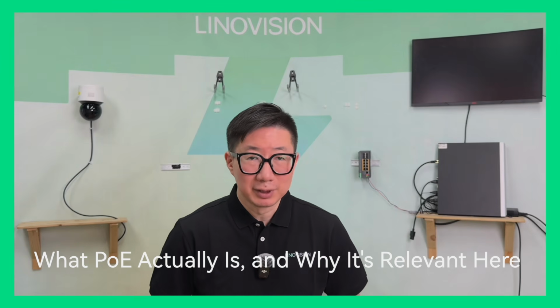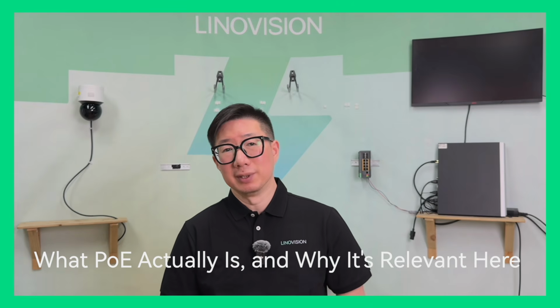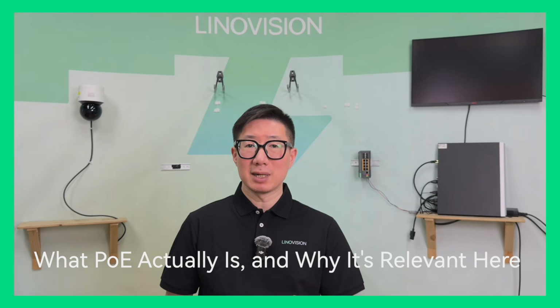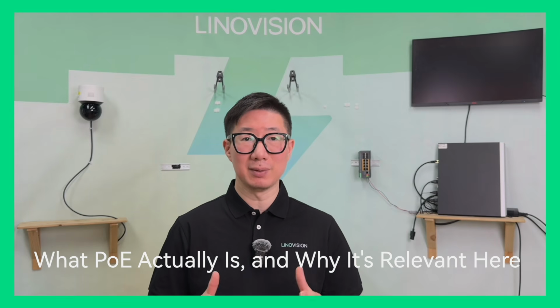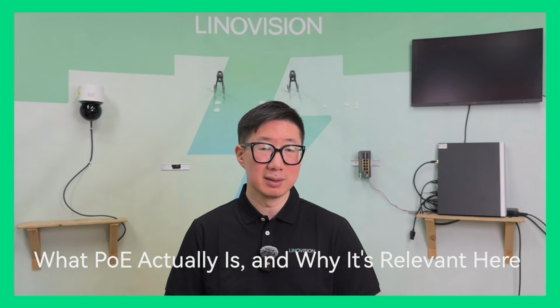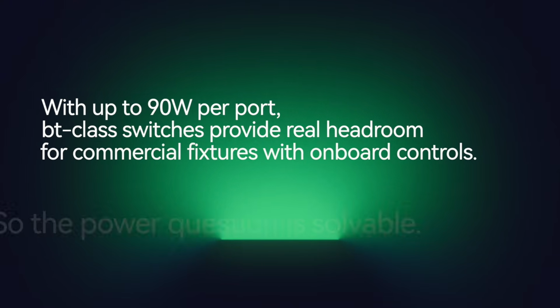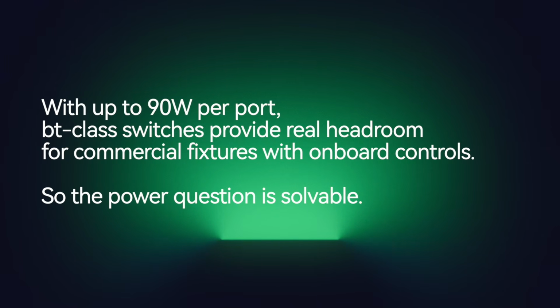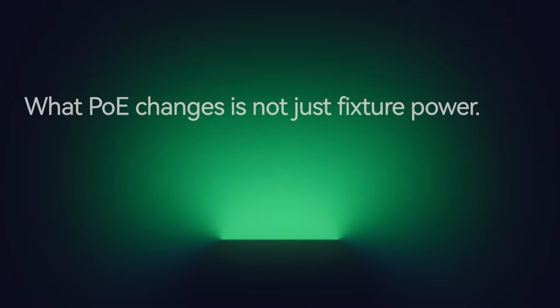Modern LED technology is dramatically more efficient than the lighting loads PoE was originally designed around. A well-designed LED fixture optimized for PoE delivery sits comfortably within what IEEE 802.3bt allows. We're talking about up to 90 watts per port on the latest BT class switches, which opens up real headroom for commercial-grade fixtures with control electronics on board. So the power question is solvable.